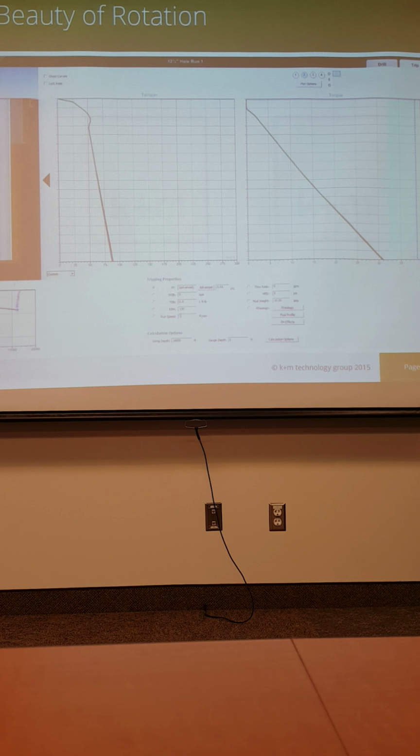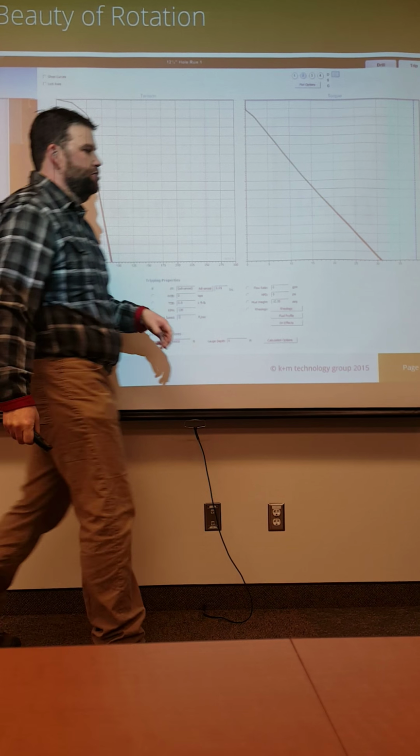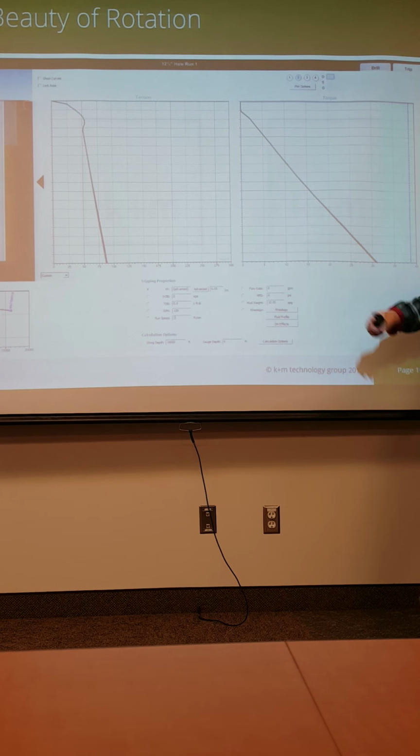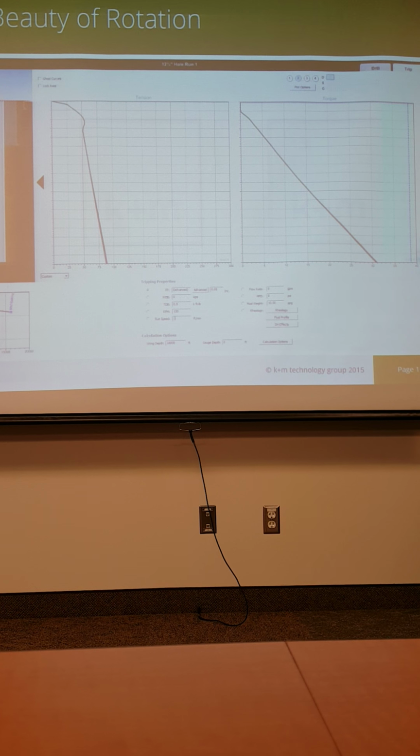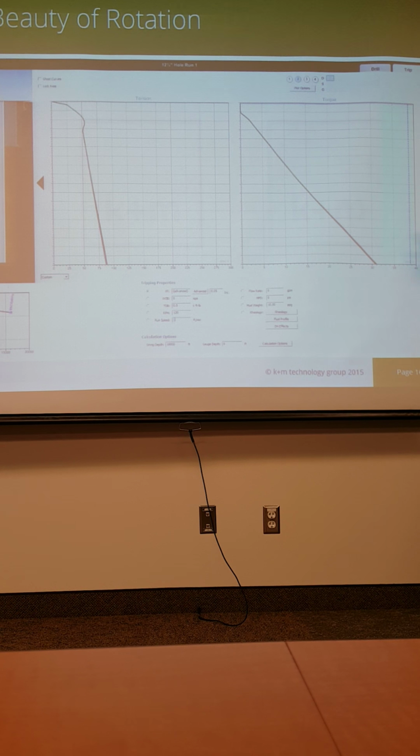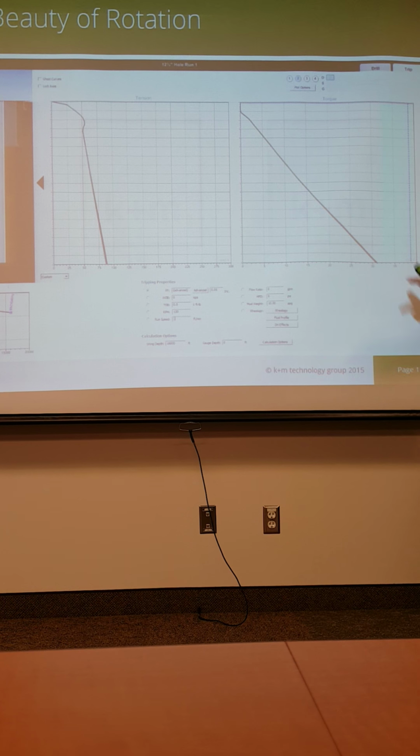Rotation is one of the most powerful tools that you can have in an extended reach well, whether we're talking about drilling, or tripping, or running casing. It's all about configuring equipment to be able to be rotated. That's why torque is such an issue. This whole conversation started with torque, but I got to make sure that this line doesn't exceed the strength of my equipment, torsionally speaking. I need strong tool joints and a strong top drive to cope with the torque that I create by turning. Does this make sense? Does it seem like it's more like a freshman level class rather than a senior level discussion?